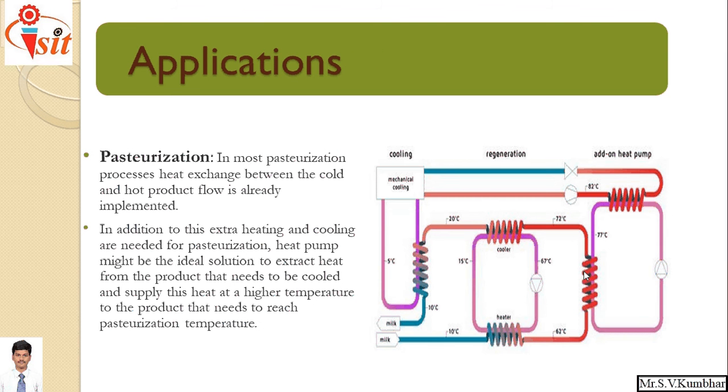The next important application is pasteurization in dairy. In most pasteurization processes, heat exchange between cold and hot product flow is already implemented. In addition to this, extra heating and cooling are needed for pasteurization. For that purpose, a heat pump is used. This heat pump might be the ideal solution to extract heat from the product that needs to be cooled, and supply this heat at high temperature to the product that needs to reach pasteurization.